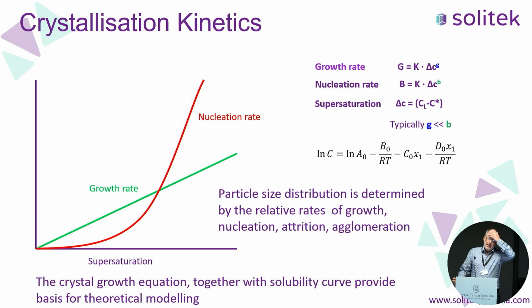So that's the thermodynamic side of the problem. And the next thing to consider is the kinetics of crystallization. Generally, for crystallization kinetics, we consider two main processes, growth and nucleation. Now, obviously, you can't have growth unless you've previously had some nucleation. You need crystal area to have growth. But one thing perhaps we forget is that both of these processes, after that point of initial nucleation, are continuing throughout the crystallization process. We have to consider both.